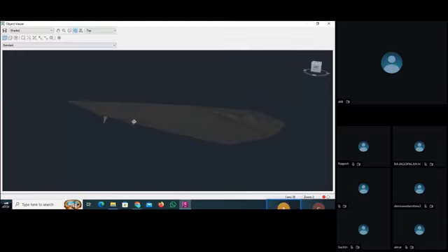If any of your points has a zero elevation, it will stick to the ground and your whole surface goes upward to the elevation points. If some point has a low elevation, this problem also happens. When you are working on a real project, this type of problem is not avoidable, so we must work on this.